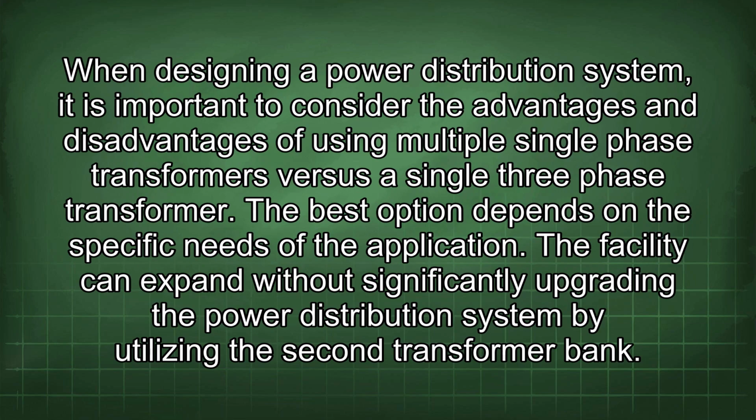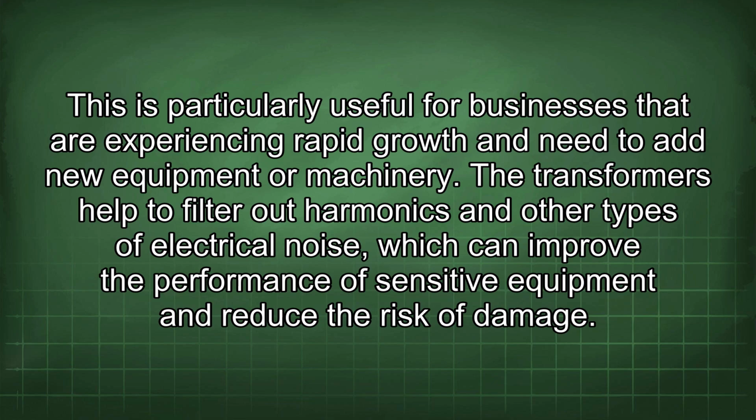When designing a power distribution system, it is important to consider the advantages and disadvantages of using multiple single-phase transformers versus a single three-phase transformer. The best option depends on the specific needs of the application. The facility can expand without significantly upgrading the power distribution system by utilizing the second transformer bank. This is particularly useful for businesses that are experiencing rapid growth and need to add new equipment or machinery.